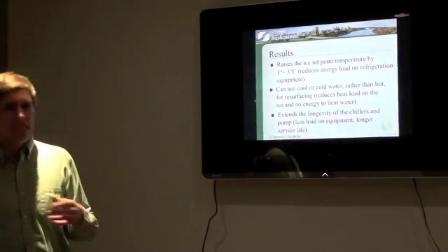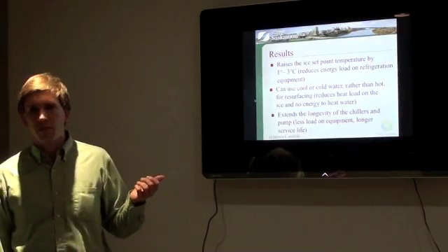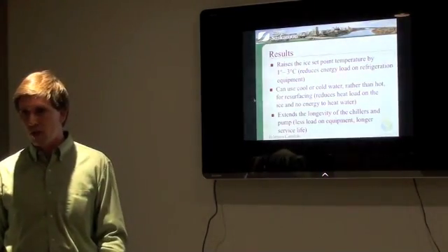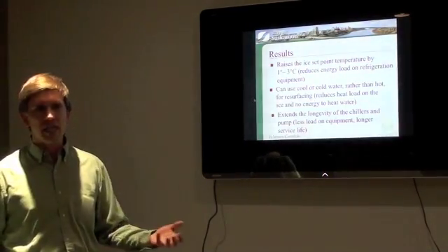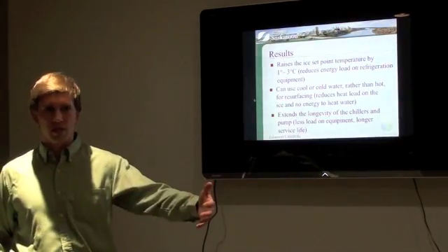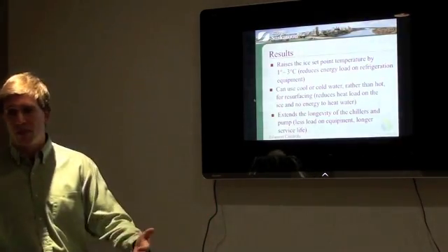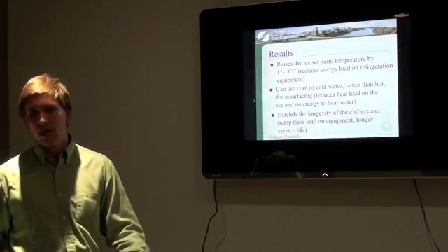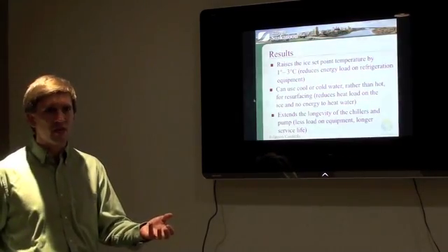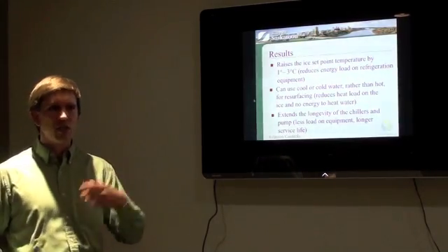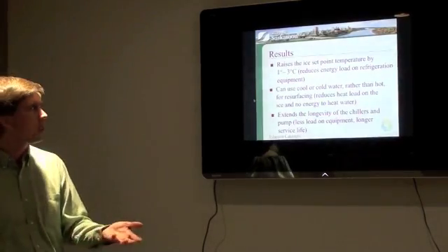As well, this extends the longevity of your chillers and your pump. So the less you need to use the equipment, the fewer hours a day that you need to use it, the longer its lifespan will be. Because if, let's say, a piece of equipment has a lifespan of 10,000 hours, well, cutting your use per day from 10 hours to 8, you've just increased the lifespan of the equipment by 20%.